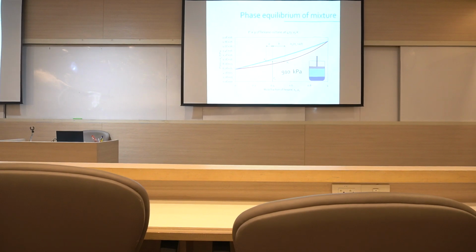That is how much you have of vapor to liquid phase. The problem with this lever rule is that you have to do some crossing, and when I say crossing, it means like this: NV over NL, so vapor to liquid. You have to find the ratio of A to B. A is now adjacent to the liquid region, and B is adjacent to the vapor region, so they kind of cross one another. So vapor to liquid equals the distance from Z to the liquid region over the distance from Z to the vapor region. So you can see that it crosses one another like that. It's a bit confusing, but that is how it is as revealed by material balance.